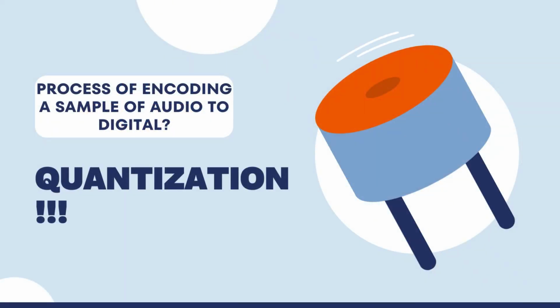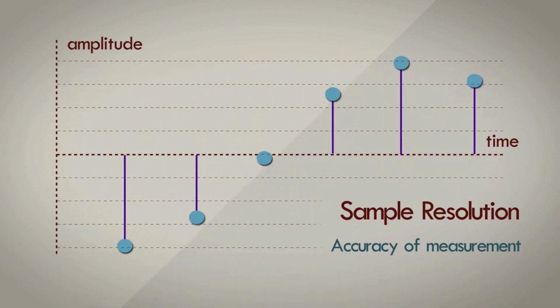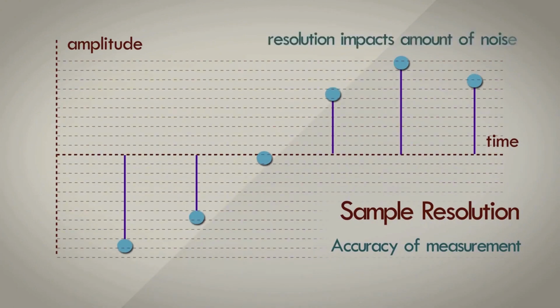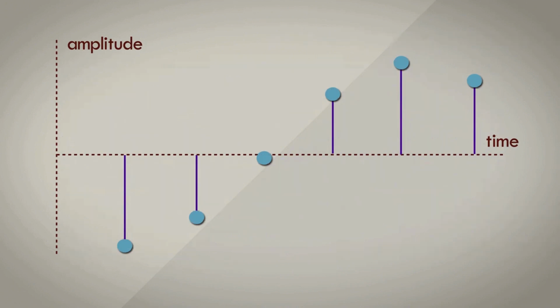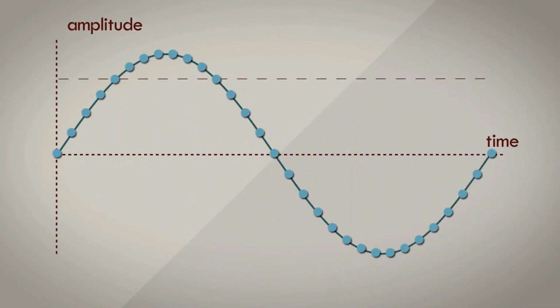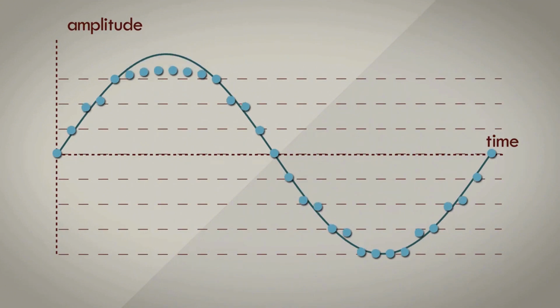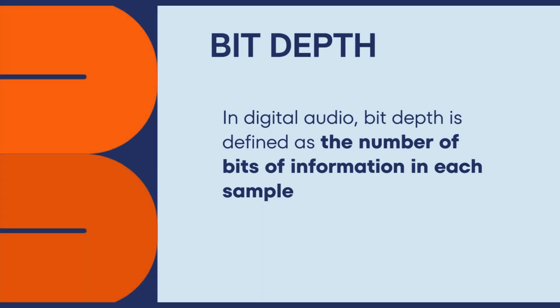During modulation, we need to encode the audio signal into digital, and it is called the quantization process. When we sample the signal, we arrange the amplitude of the signal into several levels. Let's take a sinusoidal signal and split the amplitude into 8 levels. Then the sample point will stick with the level of measurement, and that's how the pulse is generated.